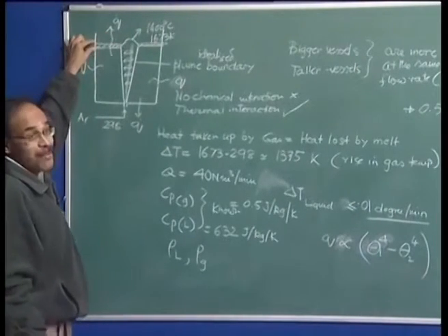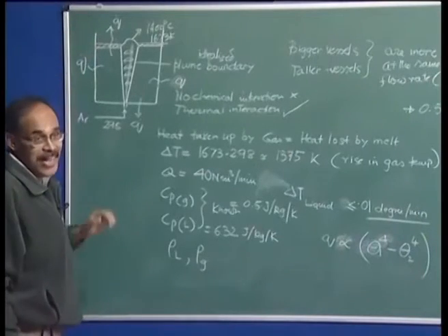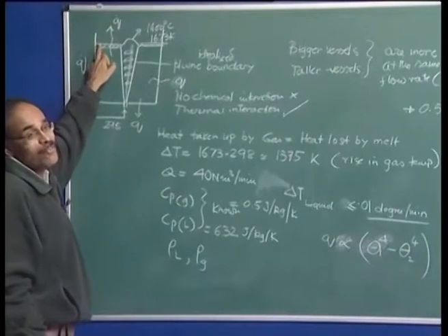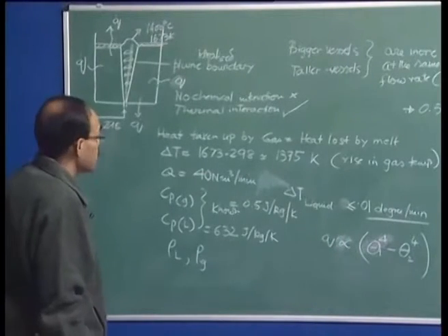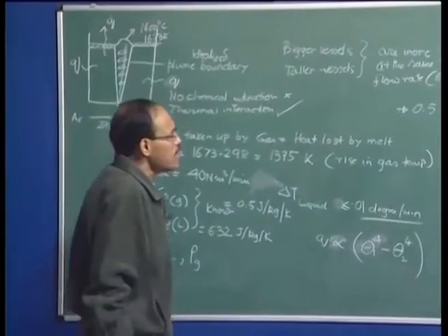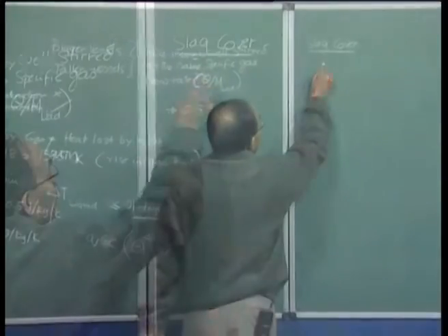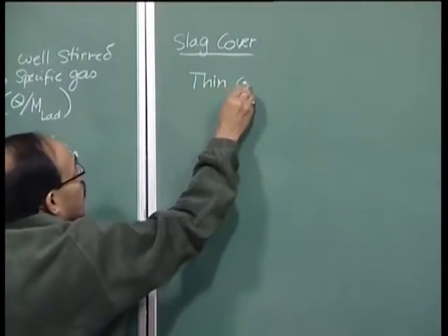And this slag, as I have mentioned to you earlier, is not an oxidizing slag. It does not contain FeO. It contains freshly prepared slag with some lime, silica, and so on. Now, basically the slag cover can be thin or thick.